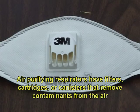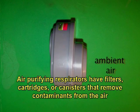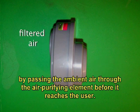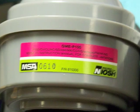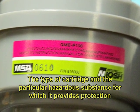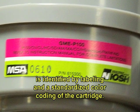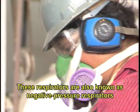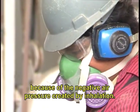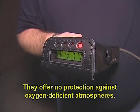Air purifying respirators have filters, cartridges, or canisters that remove contaminants from the air by passing the ambient air through the air purifying element before it reaches the user. The type of cartridge and the particular hazardous substance for which it provides protection is identified by labeling and a standardized color coding of the cartridge. These respirators are also known as negative pressure respirators because of the negative air pressure created by inhalation. They offer no protection against oxygen-deficient atmospheres.